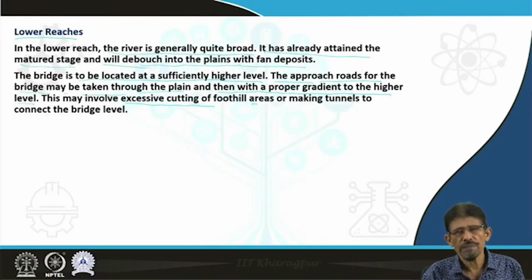As the river valley is broader than the river valley in plain area or upper reach, therefore a long bridge is required to construct, which requires a number of piers to be located. Some of the piers may be located within the water body. Needs special precautions and techniques for pilings and others.